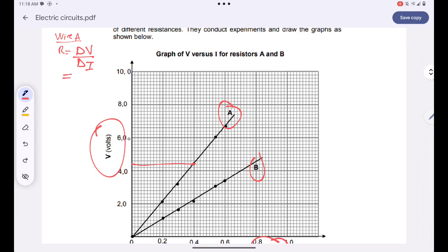There are two numbers between these 10 lines, and those two numbers are 0.6 and 0.4. If I want to know the value of each line, I just need to say 0.6 minus 0.4, divided by the total number of lines. We have 10 lines, so it simply means that each line is 0.02 apart from one another.